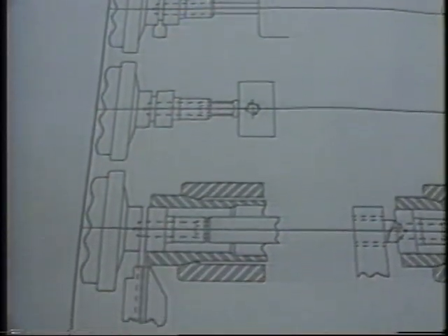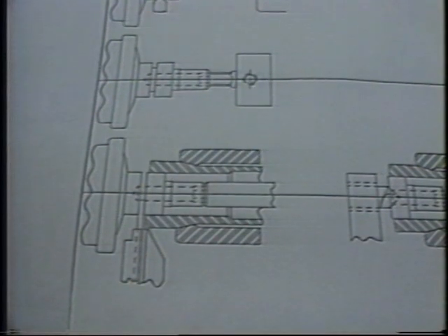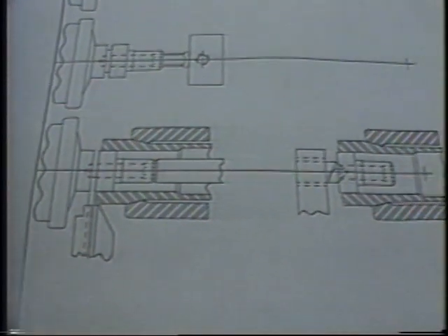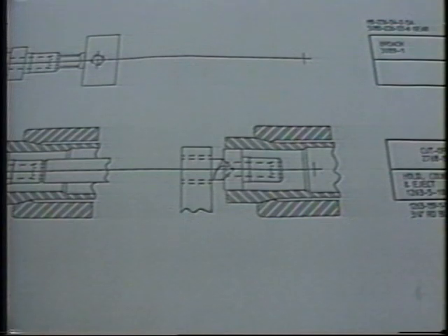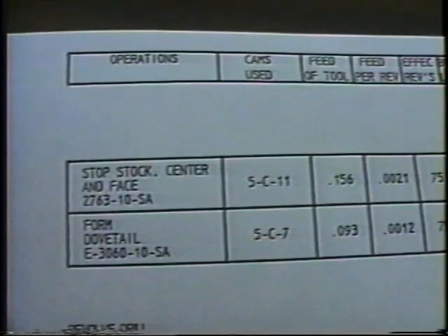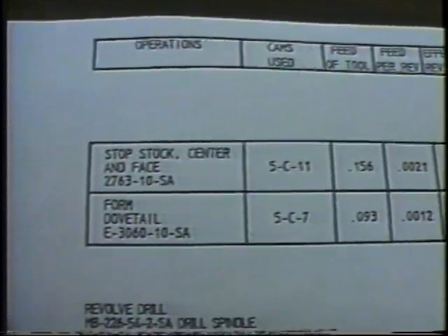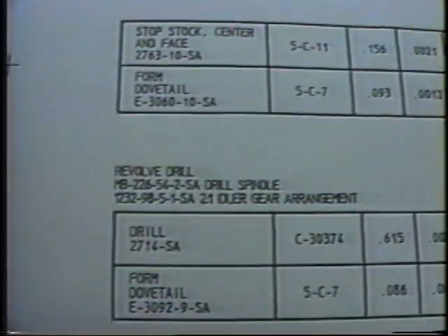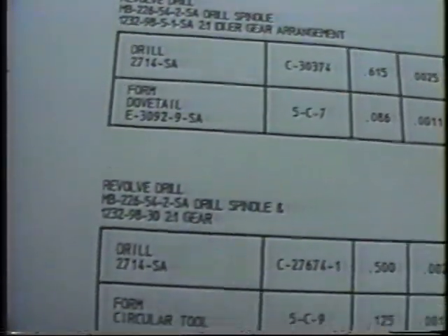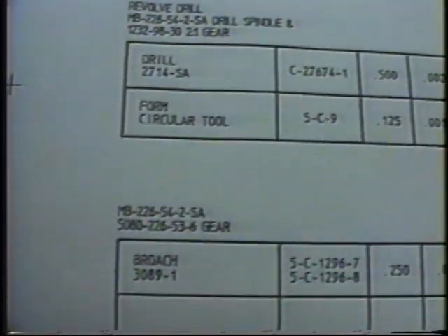Machining operations are illustrated by individual stations, starting with the first position and progressing downward sequentially to the 5th position, followed by any backworking operation that may apply. To the direct right of each machining illustration are the operations listings for both cross-working and end-working tools.